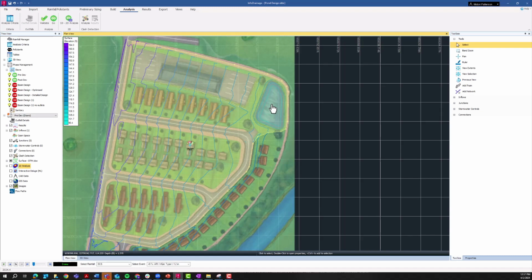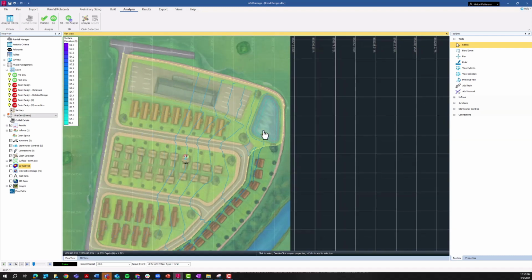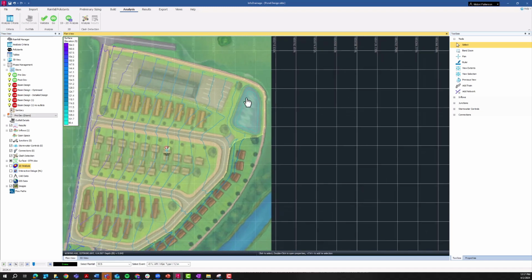Sometimes you have to detain the 100-year event. Sometimes you just need to provide enough storage for that water quality event. Sometimes it's a combination of each and you can get some credit towards that 100-year detention for those water quality simulations. So of course this is all going to depend on your jurisdiction, how much water you are supposed to detain, as well as the runoff rate.